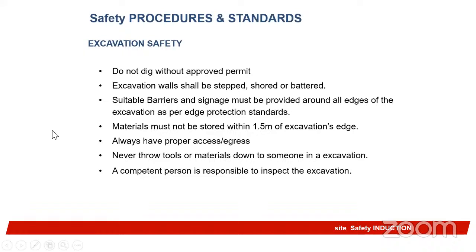So excavation safety. You talk about the excavation. It should be short. Maybe it should not be straight. You know, most times when you go to some sites, they have a deep excavation. They just make it straight vertically. The edge should be sloped, like a gentle slope.